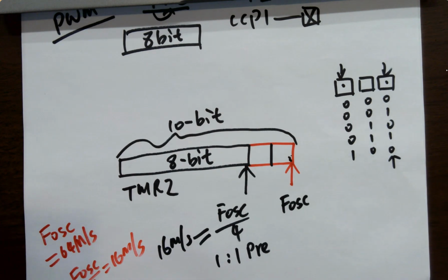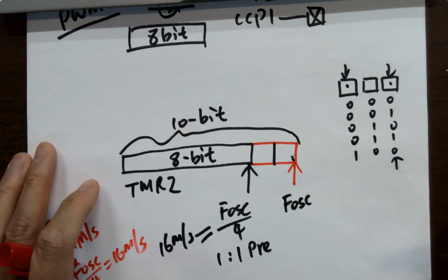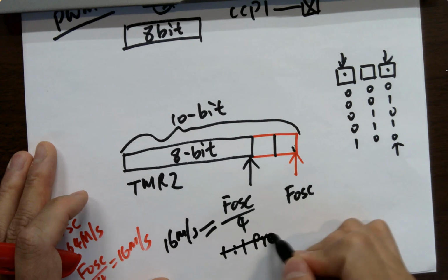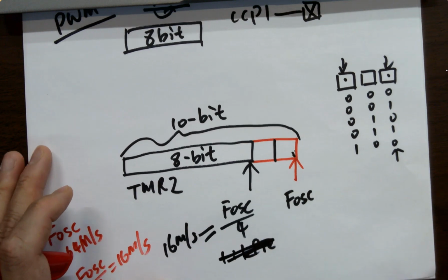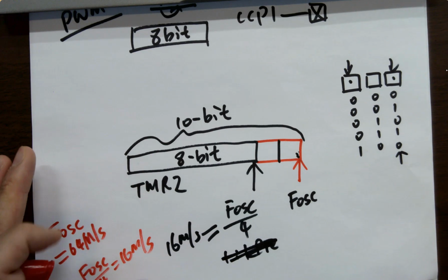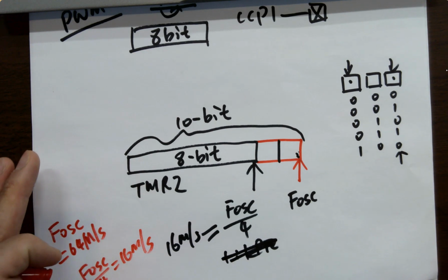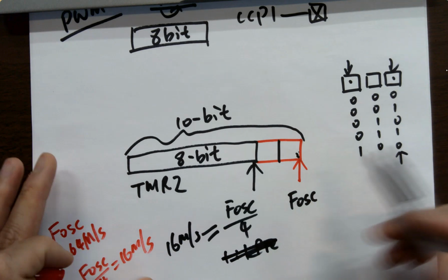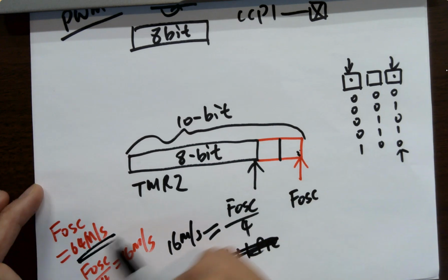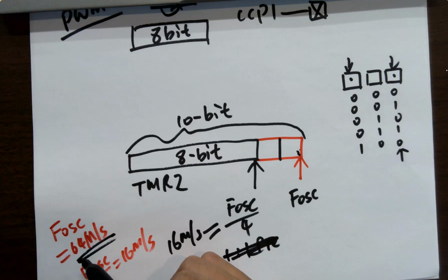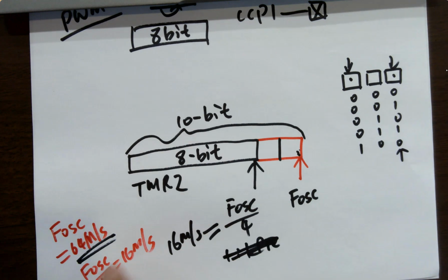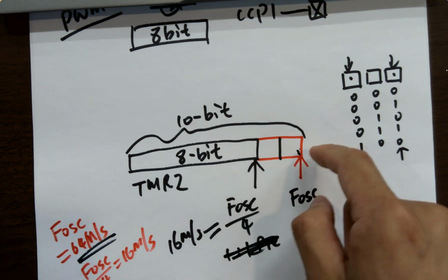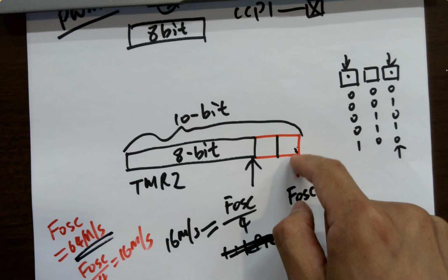Keep that in mind, all right? The actual timer, when it's working in the board, is utilizing the 64 megahertz clock, but it's just padding with those extra 2 bits that it's counting. Yes, you do have 16 megahertz. That's the fastest frequency you have on the chip, and it's being divided by 4 to support the CPU and everything else. So you get higher speed whenever you need it, but you don't use it all the time.